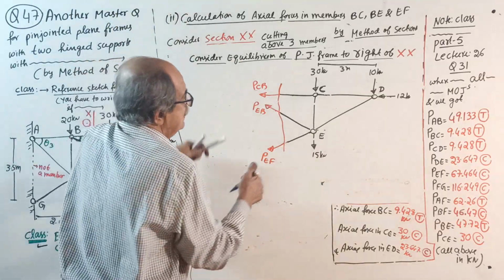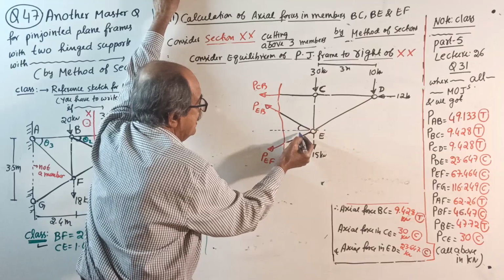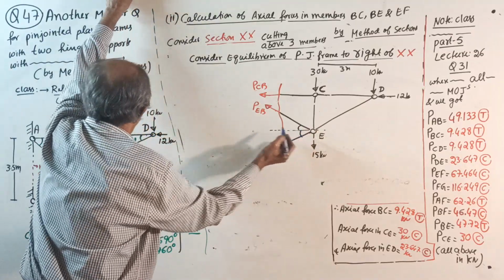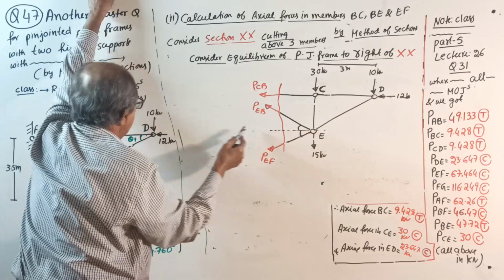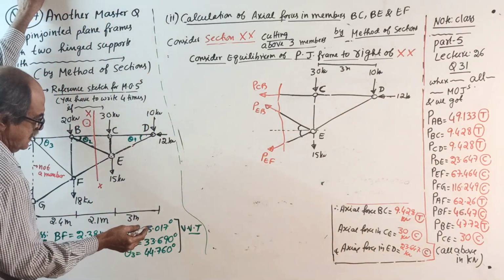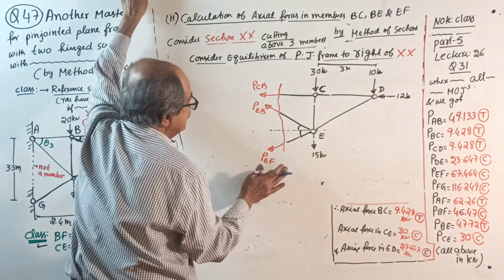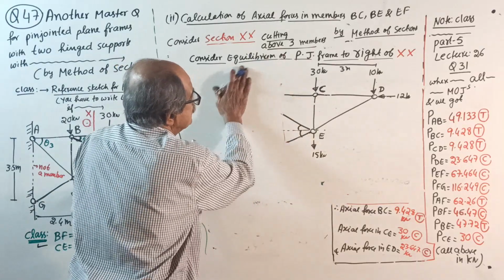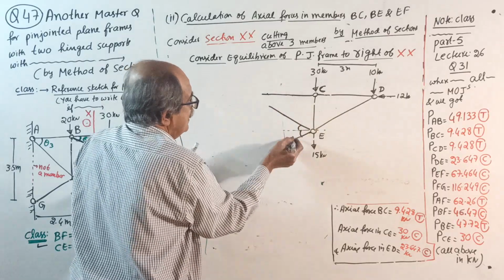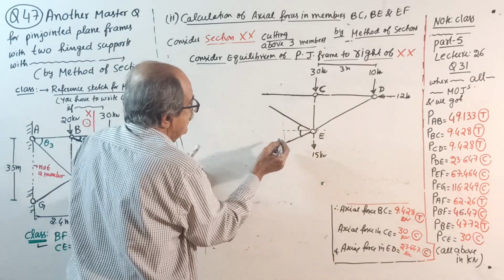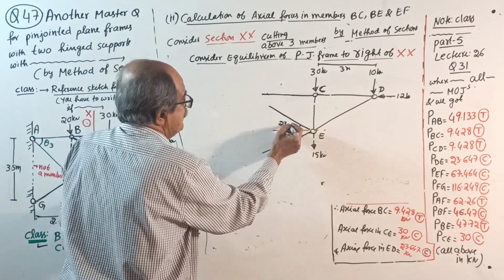Now, there are two inclined members. So, light line mark here. You require this angle and this angle. The angle made by this member with horizontal is theta 1. How much? 23.017. I think I should take a little more length on this side, there is no space here for writing the angle, so that I can mark the angle clearly. 23.017 degrees.